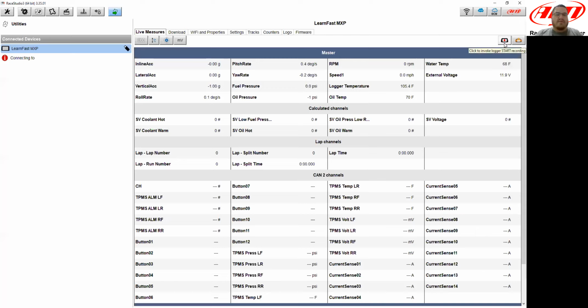You can start and you can stop. So if you wanted to create conditions, you're using a dyno, but you don't want to go change your configuration to have GPS forced over. You're on a dyno, you have only RPM maybe as a common trigger. So come over here and you can start recording. It's going to continue until you tell it to stop. Once you've stopped it, you can go and download it and look at it.